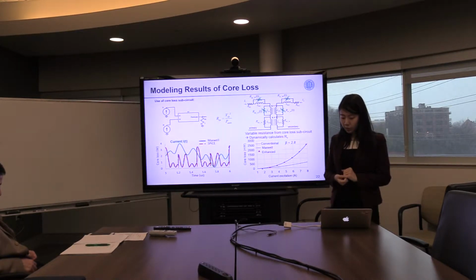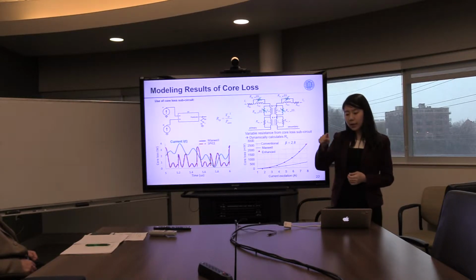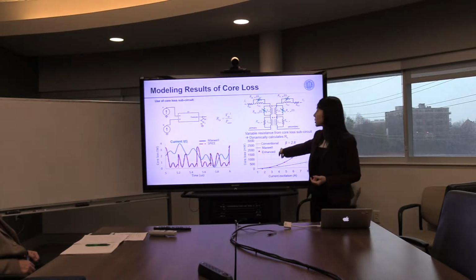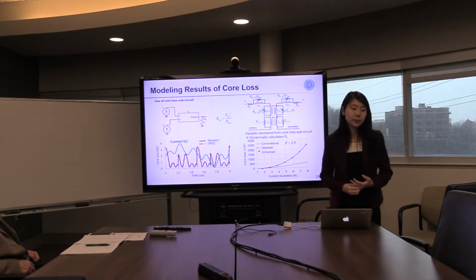The methodology there is to calculate the hysteresis of the material for a dynamic minor loop. So when the current excitation changes, it doesn't have to be a periodic waveform; it can be a transient waveform, and it is based on calculating the area of the minor loops to get the core loss. So in Maxwell, yes, and for the SPICE model we developed, we use the same model.